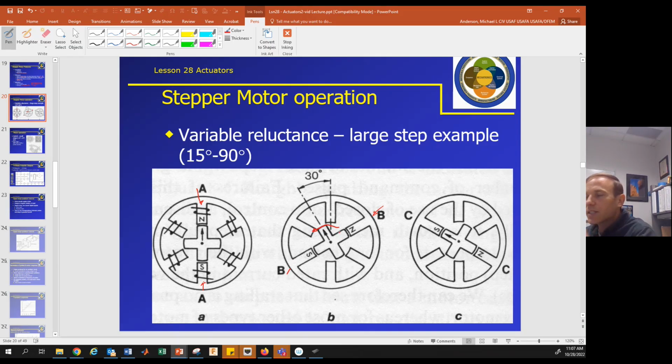And with this type of design, we see this is kind of offset. We notice the rotor is at a 90 degree angle here, and these outer stator windings are at 60 degrees. This allows us to get half steps in between the different phases. So in general terms, we'll turn on these windings in a certain sequence, and that will cause the rotor to turn around the stator. And because of the way these are designed with so many little steps, you can position the rotor at a certain position fairly precisely without needing any external sensors.